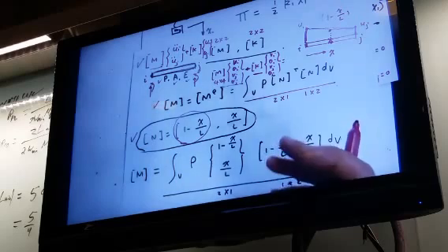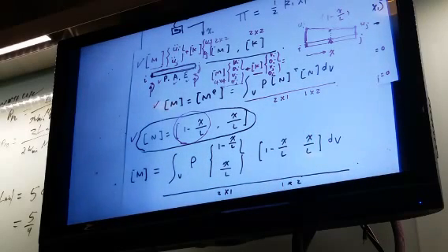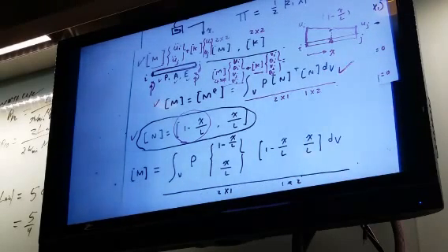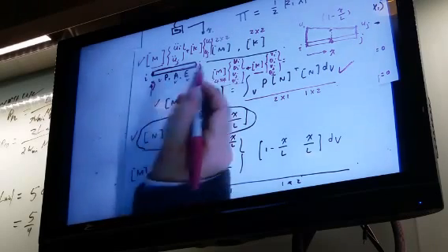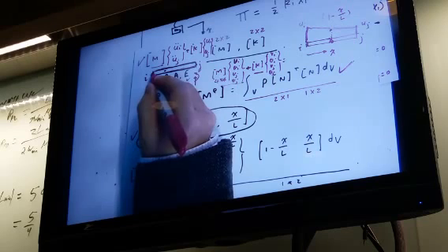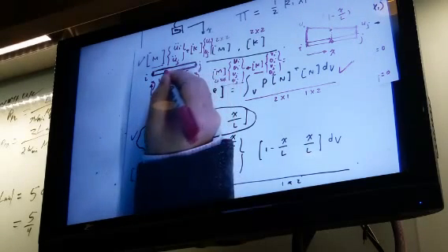So the only difference for vibration analysis from the stiffness matrix analysis is that we need to construct M. This formula for M is universal. We always use this function. But you need to tell me what the interpolation is, how you are going to interpolate the displacement within the element. How are you going to tell me the displacement here if I can solve for the displacement at the two points? That is flexible.